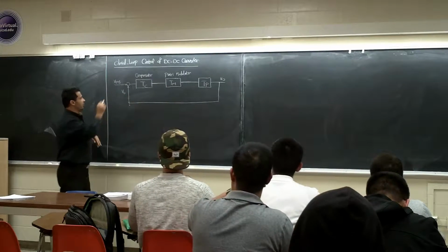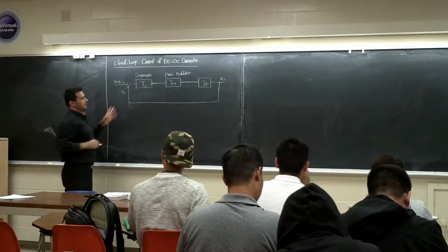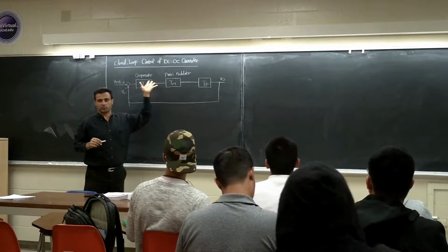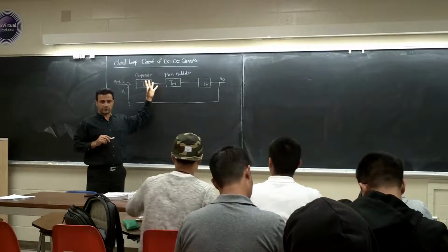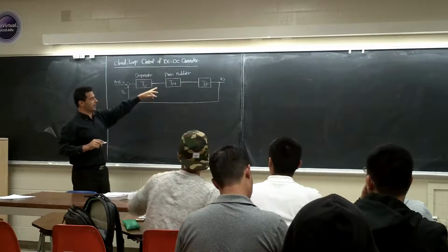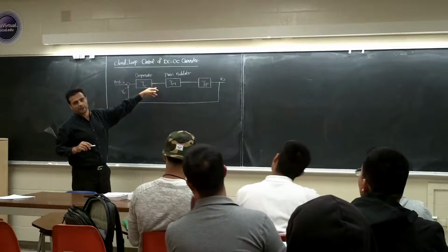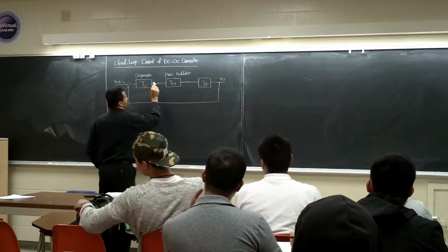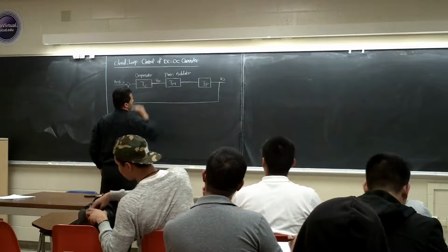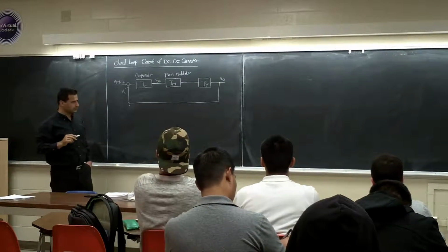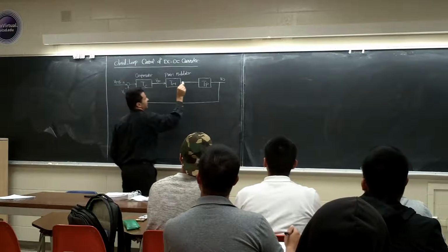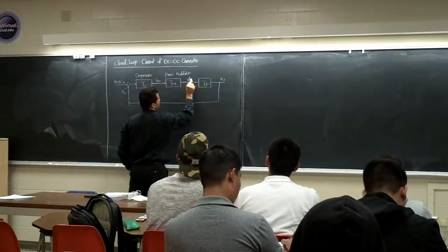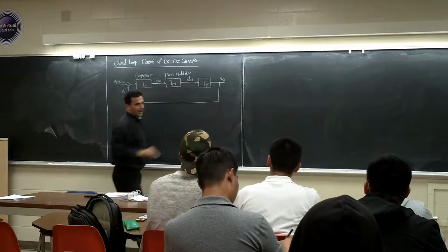Here we are going to have an error signal, right? This error signal is going to come to this transfer function, whatever it is, we're going to talk about it. So this transfer function, I think I made a mistake. Here I said D, but this is basically V control. The V control coming here, output of this one is a D. Duty cycle, going to the plant, right?